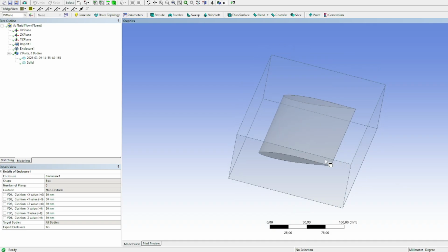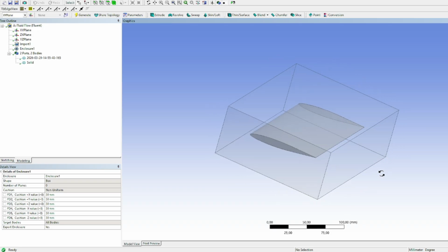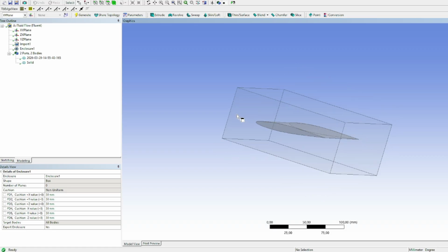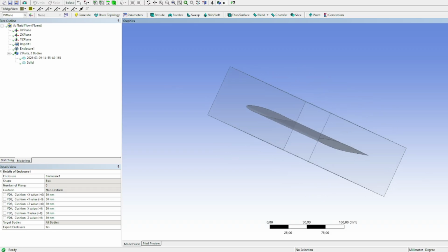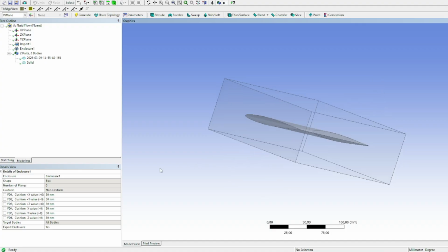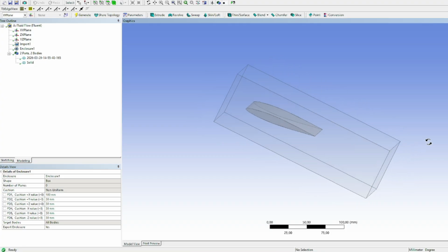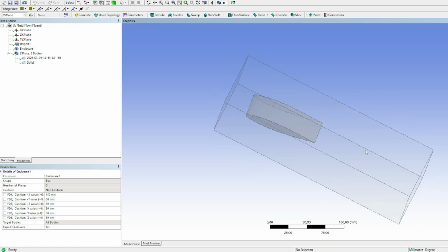Okay, first of all, we are gonna change this face that is in the axis X positive. If we click on X positive, it will bring us to this face. So we come here and we will put 100 millimeters, or even 150 millimeters to make it more realistic.